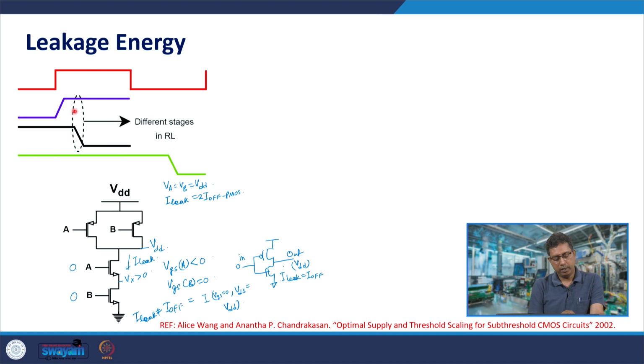You would observe that the NAND gate has just a leakage current, its switching happens only here, and it has this leakage current for most of the logic operation. Likewise, the NOR gate has leakage when its input is VDD and again leakage when its input is 0. Its leakage current's value may change, but it has a leakage current for most of the clock period, likewise for the third stage. So, for most of the clock period, it is the leakage current which flows through the logic gate.